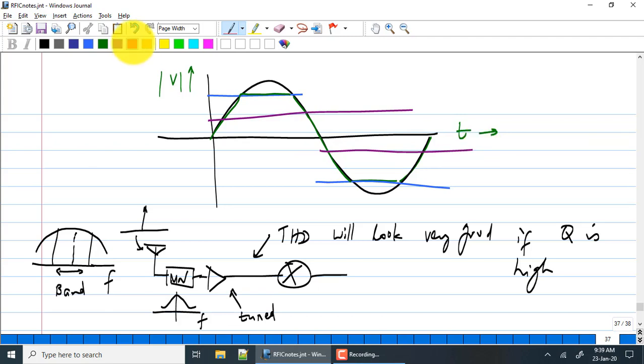So in the limit, it will just look like this, something that very closely approximates a square wave. If I increase the input power, that square wave amplitude will not change. So in the end, all of the power that you are giving in to the input sinusoid will get transferred by the circuit to higher harmonics, which then get filtered out anyways. You understand? So what will happen to the output power? It will stay the same even though I am increasing my input power.